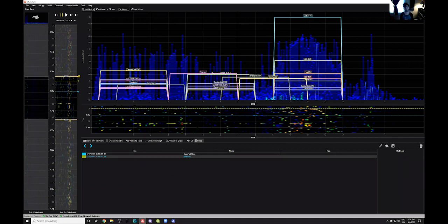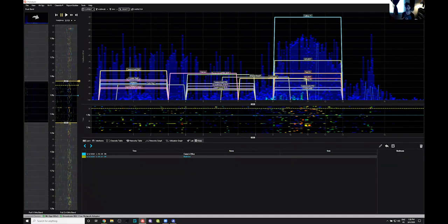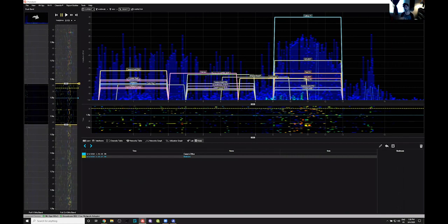The Wi-Fi DBX is a 2.4 and 5 gigahertz spectrum analyzer. You can get a little bit outside of those frequencies with it. I believe we're going to have to ship a new piece of hardware to accommodate the 6 gigahertz band. I think the 6 gigahertz band is just too wide to be able to use the DBX, but I'd have to check with our hardware engineers to be sure. Most likely we will have dedicated hardware, it might be called the TBX, the tri-band spectrum analyzer: 2.4, 5, and 6 gigahertz.